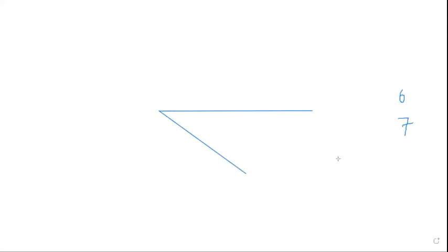So at this, and it will be 7 equal parts. By using the compass, take any measurement. Okay, you divide it into 7 equal parts. So suppose this is 1. Any measurement, you can take 10 millimeter, 1 millimeter, any measurement by compass, you can divide into 7 equal parts.